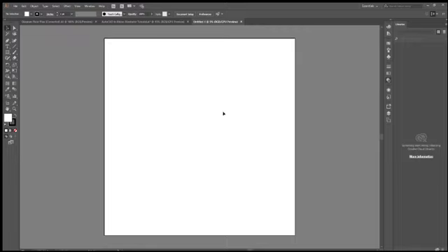So when you open Illustrator for the first time, it should look like this. We'll go over more details in Illustrator next week. But for now, if you open Illustrator, you should have some kind of a white backboard on your screen and your interface open like this. If you don't, simply go to File, go to New, accept whatever this gives you by default. It's an extremely large paper size. Again, don't worry about it. We'll go over how to change those in the next class. So we'll just say create, and then it gives you the white canvas. So we're now ready to open the Illustrator file.